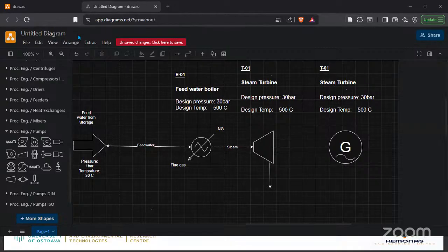Please give me a minute to take this call while you send it into the chat box. Yeah, before you go, sir, where should we place the pump? You need to place the pump immediately after the battery limit. It should be the first equipment before the heater. Okay.